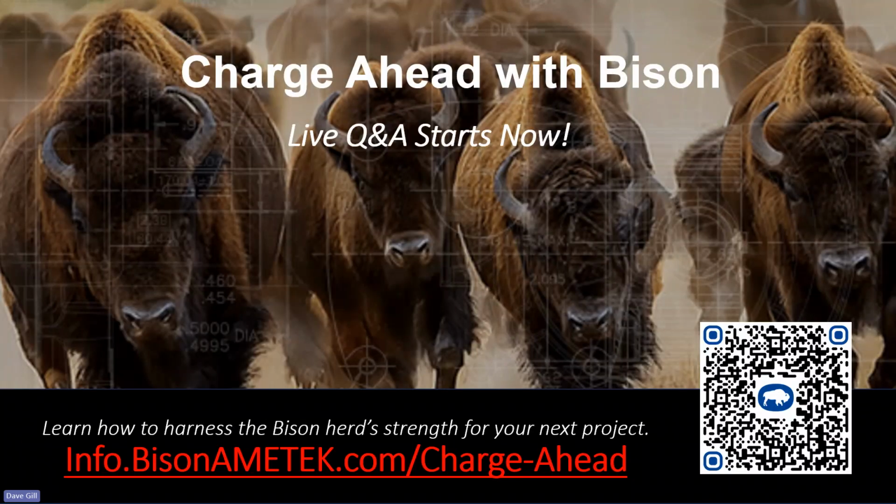You get less I squared R losses, so that keeps the temperature down. We sometimes would need to do something to guide the air better. If it's a motor that we can improve baffling on or something like that, so that the CFM that you do have are going where they do the most good. Things like that. We need to know what your constraints are and what your product is like and how we can customize the motor to work best that way.